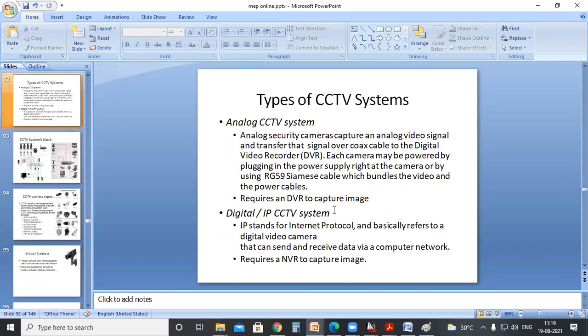And also the budget. When you see the drawing, you can mention this in the drawing. You can provide the range of area from the site plan or whatever plan, the architectural plan you have with you. While observing the plan, you know this camera will be suitable for this particular area, dome or bullet, based on the application and range. You can also mention it in the drawing itself: this will cover this much area if provided at this angle and position. The practical condition could be a little different from the drawing we have provided.